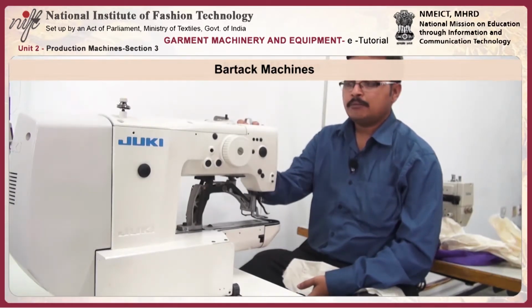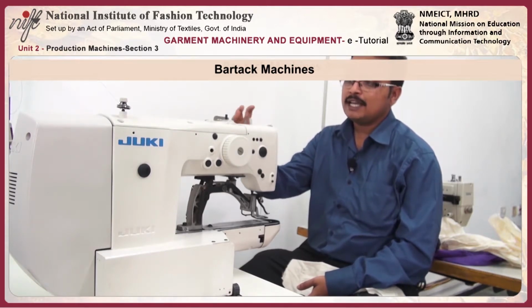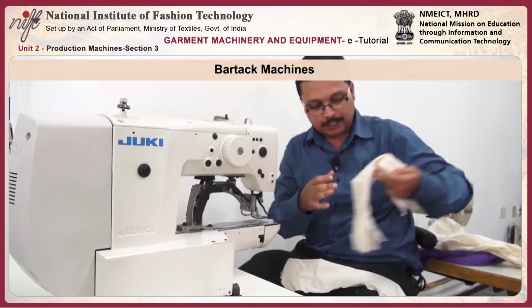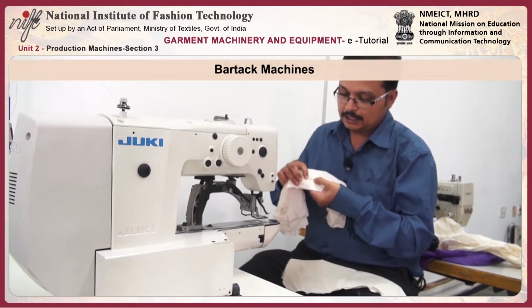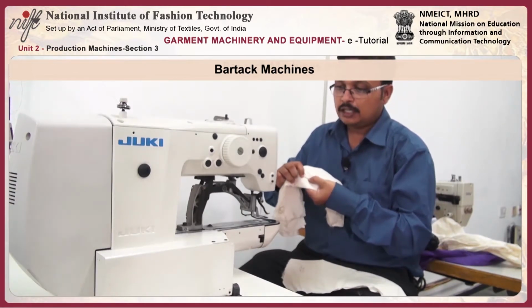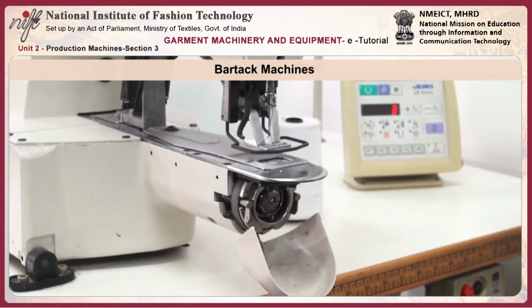This machine is known as a Bartack machine. Basically, this machine produces zigzag stitches in a concentrated manner, something like this. The idea behind that is it gives reinforcement by giving lots of stitches within a short length of fabric. Since the stitch type produced here is lock stitch, stitch class 300, you can find the needle and bobbin mechanism in your view.